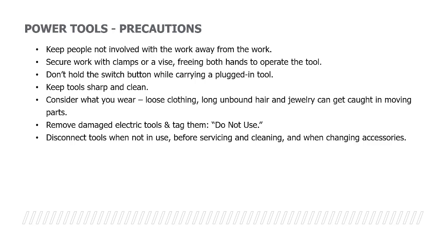Disconnect the tool when not in use, before servicing and cleaning, and also when changing accessories. Okay, you say, what's changing accessories all about? A good example of that would be if you have an electric drill and you're going to put a new bit in that particular drill, you need to unplug it before you use the chuck to remove the drill bit, and the same way when you put a new drill bit in, you need to tighten the chuck back up, and then you proceed to plug that particular drill in.